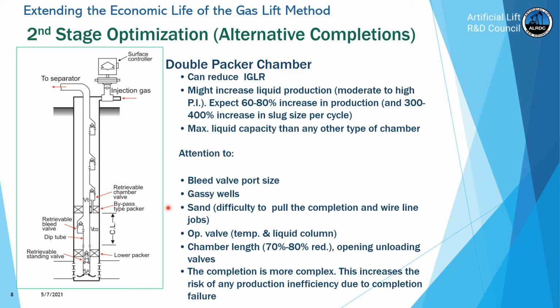If the well is producing sand, then this type of completion is not recommended because it might be difficult to pull the completion or perform wireline jobs. We do have special designs for the standing valve, so that it will clean itself every time you inject gas, getting rid of the sand that accumulates here.